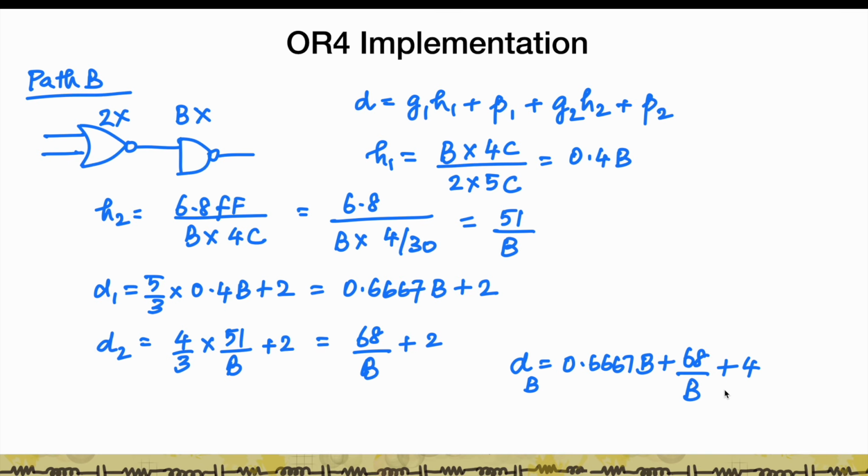Right? So you see an interesting thing here, which is known in the logical effort world. The size of this stage affects the previous and this delay, right? If I make this size larger, it makes the delay of the previous stage larger, but makes the delay of the current stage smaller.